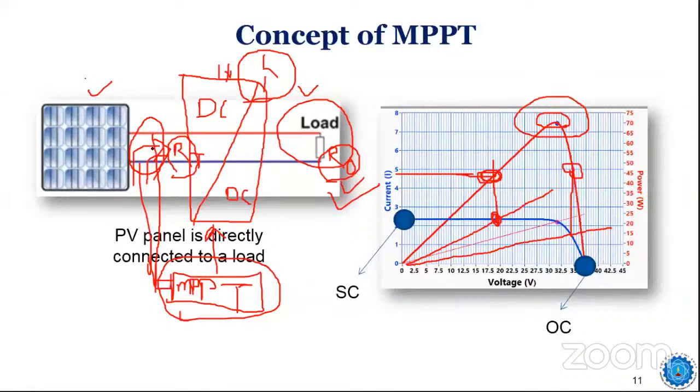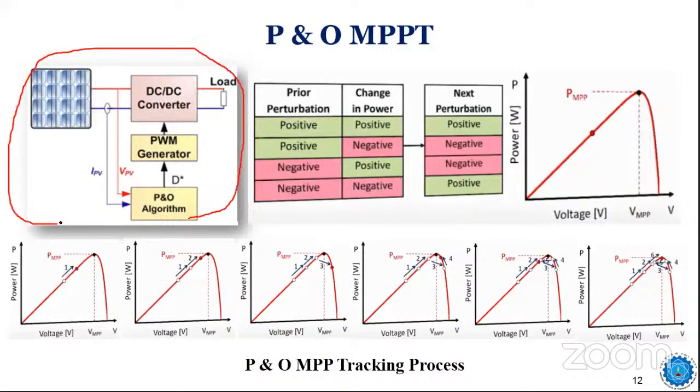And in this type of system, by sensing the voltage and current output from this point, we first get what the power should be, and we slowly try to track that global or maximum power, right? So that is how these systems are developed. This is the basic block diagram of a photovoltaic system. Neglecting the load, after this you can connect an inverter, the grid or anything, or a battery can be connected, any type of system. So this is how our systems look, where we are trying to isolate the load and the input resistance, the terminal resistance RT, right?